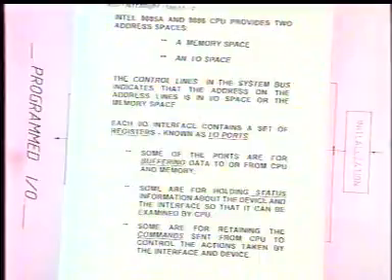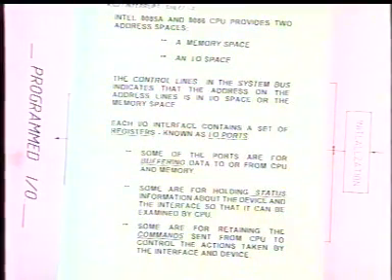So basically, one can say the interface is hardware which consists of certain registers: data buffers for input as well as output, and a command register, which will hold the command generated by the CPU to decide whether it has to do reading or writing. Then there is the status information, which is very important, because some of the peripherals are normally slower than the CPU, as a result of which there must be status information to say whether the peripheral is ready or not.